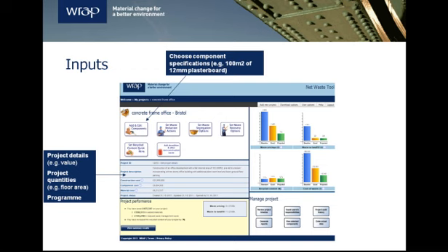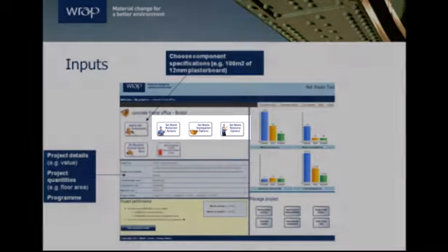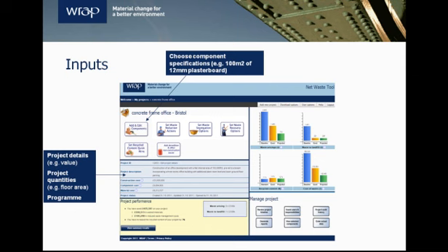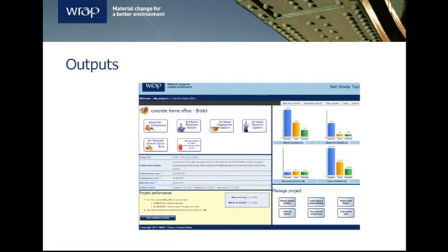Once the component data for your project has been entered, you can move on to the next step, analysis. The analysis stage will help you identify how to reduce waste and increase segregation and recovery. You can also investigate opportunities to increase recycled content. Module 3 explains these tasks. Post-construction, you can upload actual waste data to the tool and compare the actual wastage against the tool's estimates. This is optional. The NetWaste tool provides both high-level and detailed results.